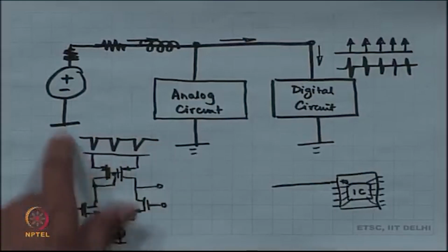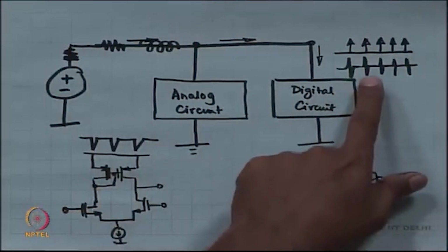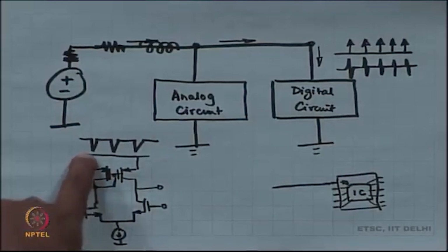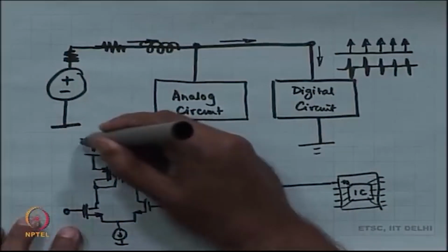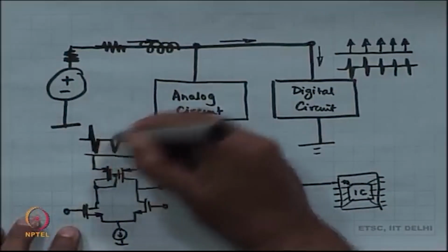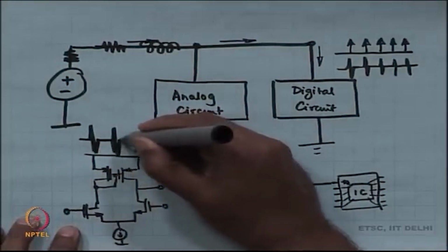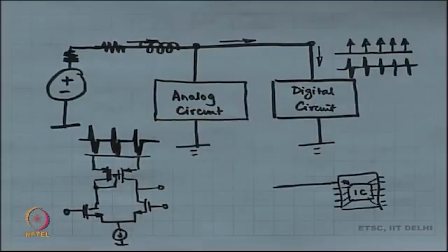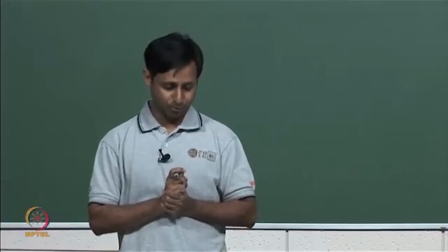So, effectively this power supply voltage is not even going to look like this. This is if you are lucky. Typically, it is going to look like this. Okay, which is even worse, and L di by dt is going to go up as the frequency goes up, right. The shorter these pulses are, di by dt is going to blow up even more and more.